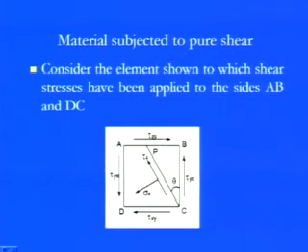Because of this tau xy, the stress distribution is there in this particular portion, and as I told you, the complementary shear stresses are there: the tau yx, which is exactly equal and opposite to the shear stresses being applied. That means there is no normal stress component in this structure, only pure shear stresses; the complementary shear stresses are there just to balance those things. Now we want to check what stress components, normal as well as shear, are there at the oblique plane.